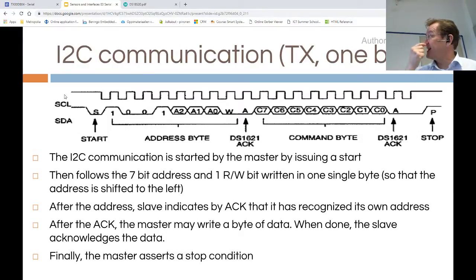When sending data, basically, let's see, does it show it? No, it doesn't show it totally correctly. So basically, these data lines cannot change when the clock line is high. Yes. So as to prevent an accidental stop sequence in the middle of data. Okay. So yeah.